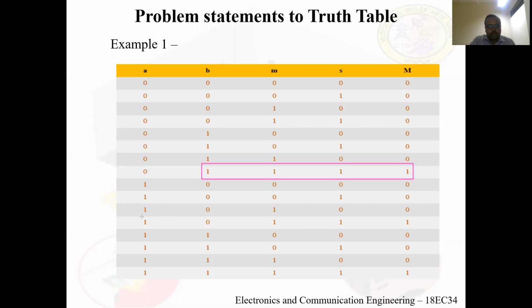You can see from this one, right? The material is present, the interlock switch is closed, and operator 1 is present. Turn on the motor. And also we have the last condition here, right? Both operators present, material is present, and the interlock is also closed. So turn on the motor here, right?